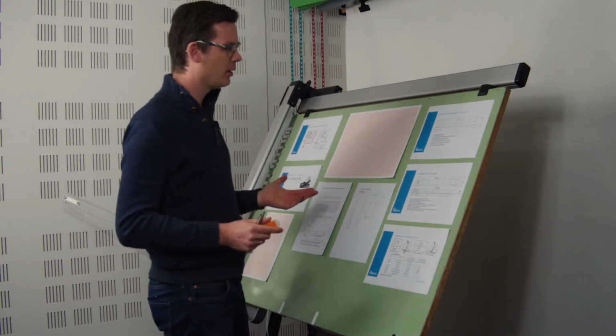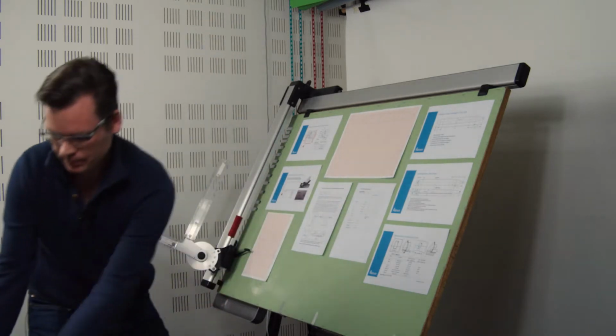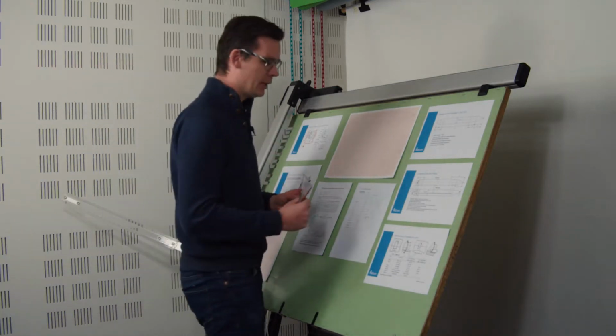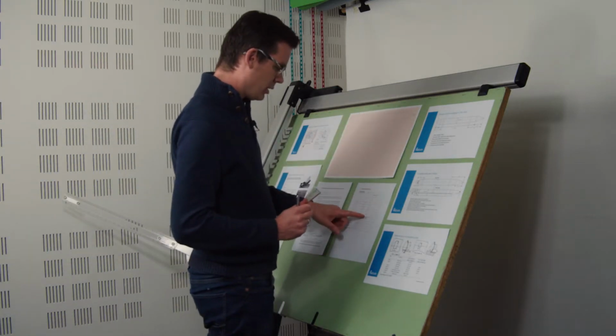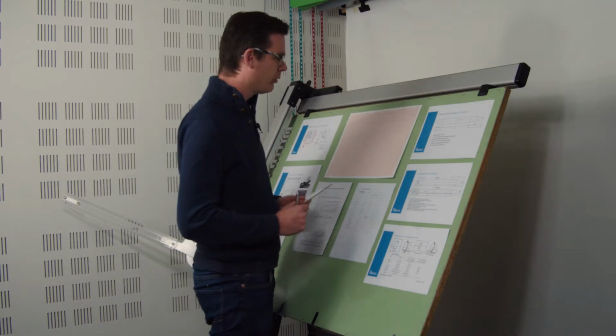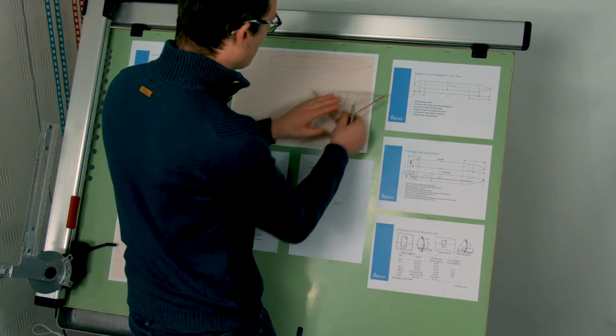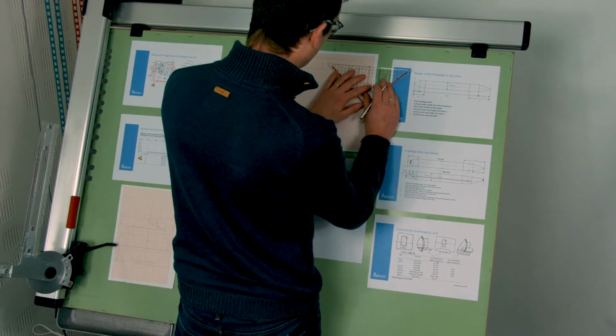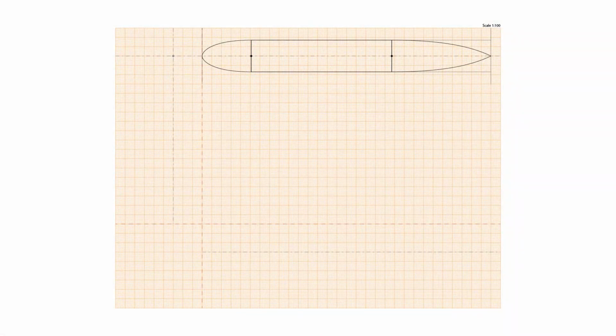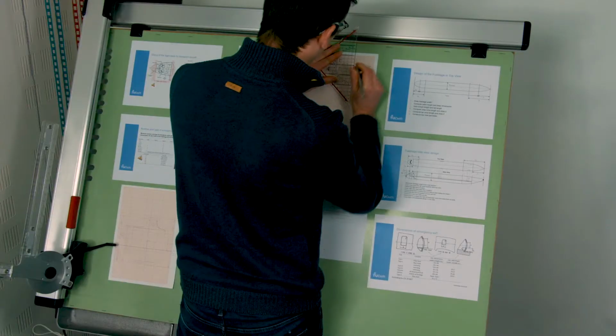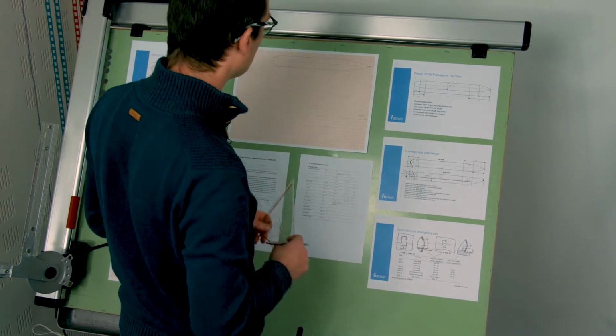The next thing we're going to do is we're going to draw in the cabin, and for that, use the protractor again. It says here that the tail length is 4.4 meters, which puts the aft pressure bulkhead 4.4 meters out from the tip of the fuselage. Drawing that in, 4.4. That's me here. So aft pressure bulkhead, i.e. the end of the cabin, is located over there.